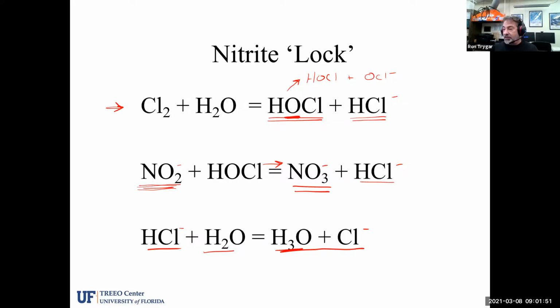So many operators notice that the nitrate number seems to go up, but they don't notice the nitrite. And if you don't measure the nitrite out of the filter effluent or the clarifier effluent, then you won't know if it's the problem or not. So you have to actually measure the nitrite before the chlorination takes place to see if that really truly is the issue with your chlorine demand.